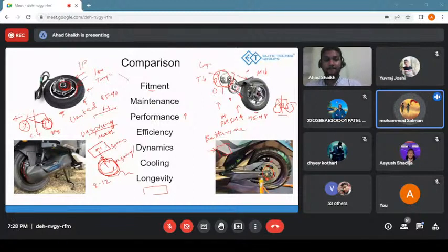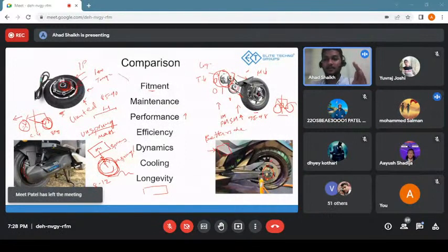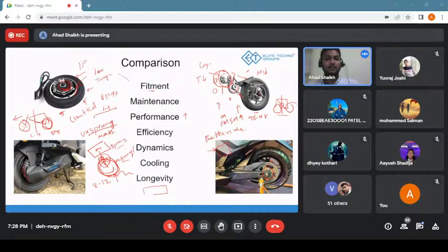front suspension system, like telescopic, upside or downside. No matter what suspension you use, Salman, the thing that comes in contact is the tire and motor. Suspension, then again we come to the sprung and unsprung mass. Suspension will always be behind the wheels. So no matter what level of suspension you use, it's the wheel that is coming in contact with the bump. So it will surely hit the motor, and it might affect the internal construction of the motor.